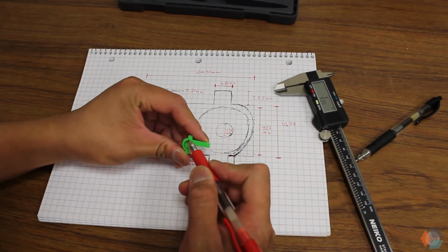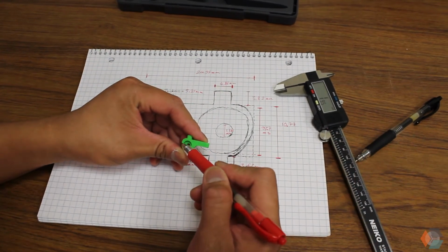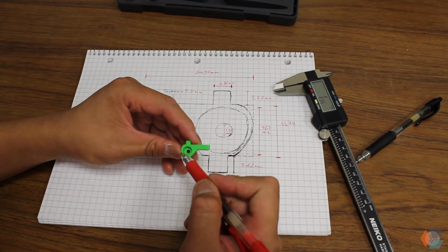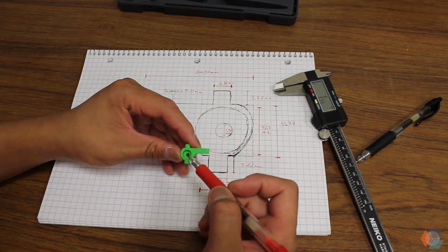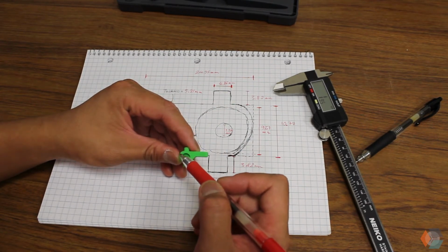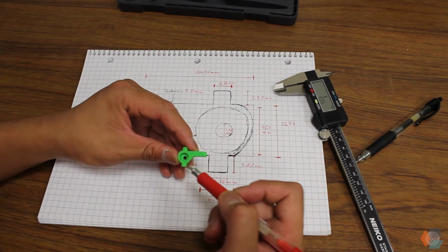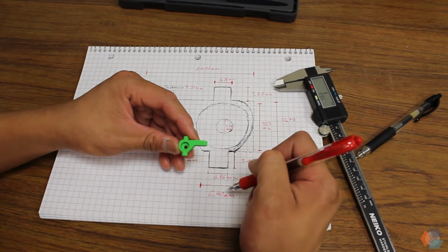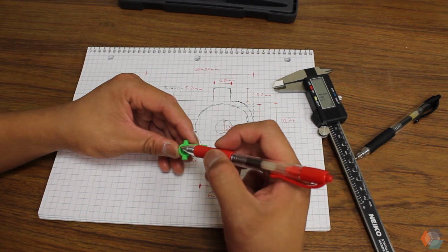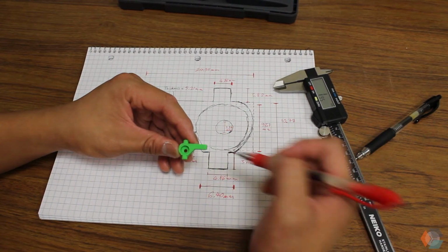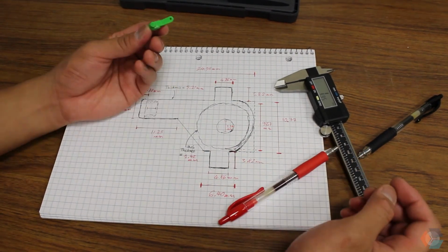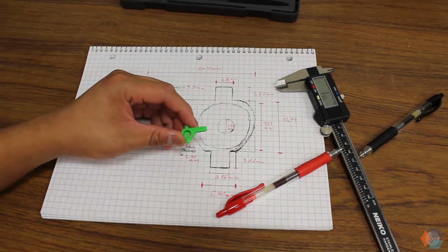And now let's look closer. Notice how there's a curve right here with a straight down line and a sort of curve in this end. That means that instead of simply making the curve itself, you can use a fillet to make this curve. So it can be a straight line when we create the overall shape, and then at the end we would fillet out the curve. Now let's move on to the next step, which is CADing in the SolidWorks program.